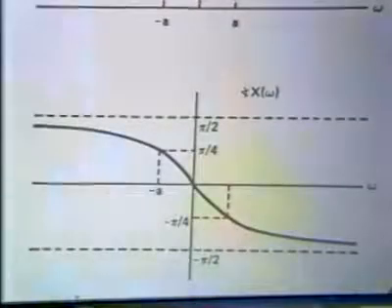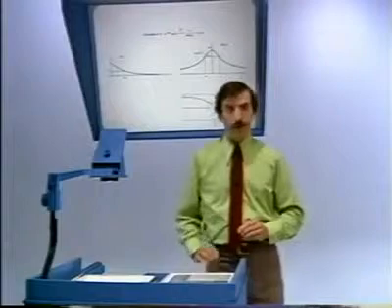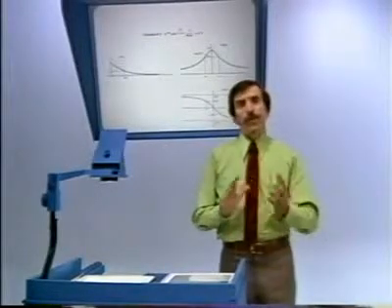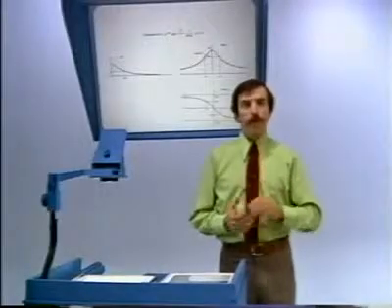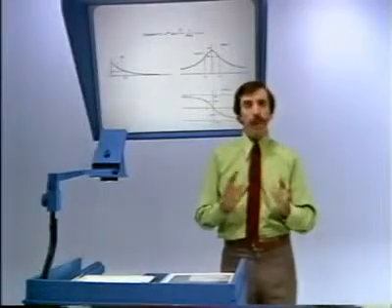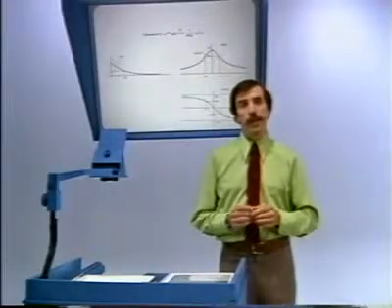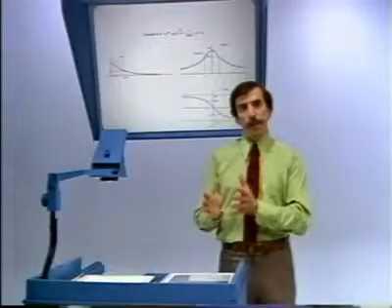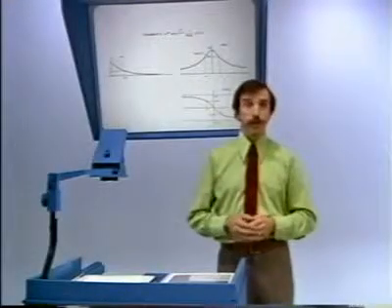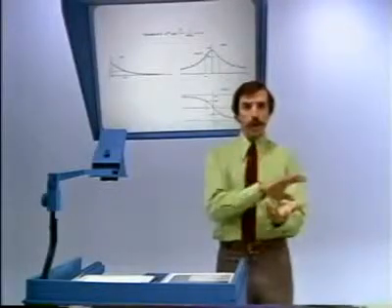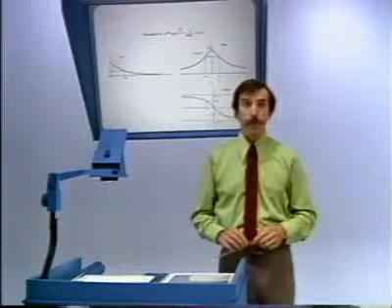So, in fact, although I stressed last time that the complex exponentials required to build a time function require exponentials of both positive and negative frequencies, for x of t real, what we see is that because of these symmetry properties, either for the real and imaginary or magnitude and angle, we can specify the Fourier transform for, let's say, only positive frequencies, and the symmetry then implies or tells us what the Fourier transform then will be for the negative frequencies.